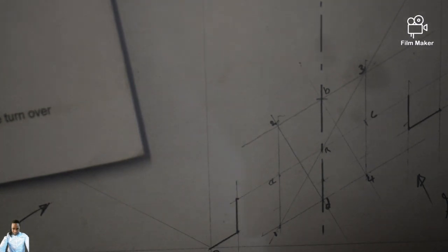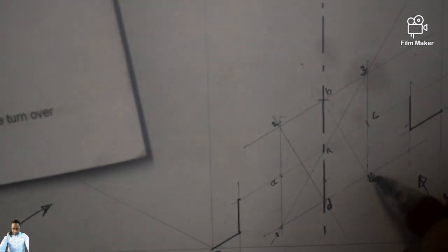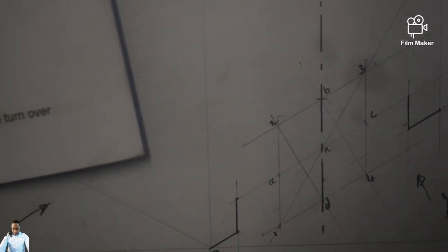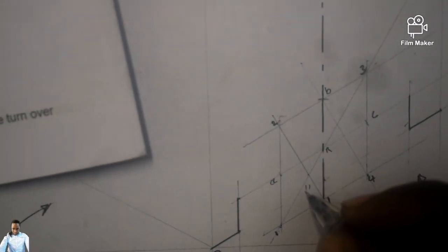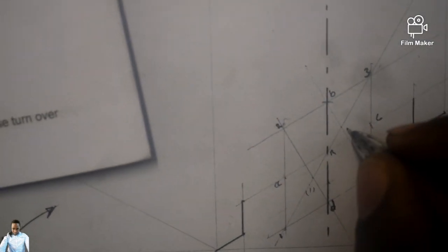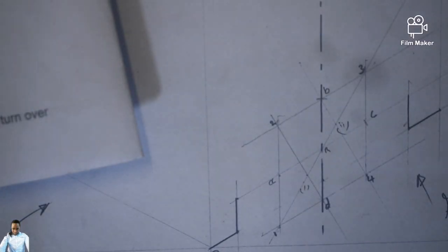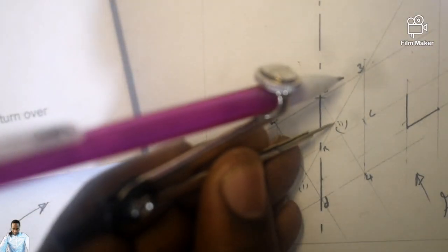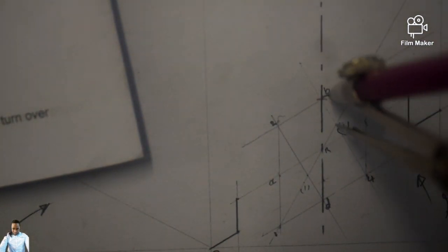So now the time we're joining the corner point to a center and the center to a corner, our line of the two longest opposite corners, they were cut. So I have a point there, I can give it Roman figure 1. I have a point there, I can give it Roman figure 2. So now I am going to take my drawing compass and place it at Roman figure 2, extend to point C, like this. There you go. And this arc of mine must start from C to what? To B. So there you go.